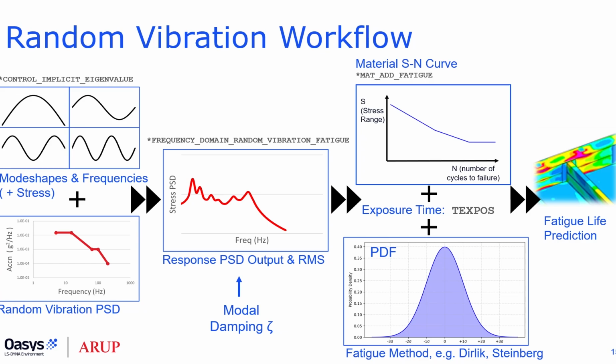With both methods, once we know the total damage, we have a good indication for each material whether it's likely to survive the test or not. But like all fatigue analysis, it's highly dependent on good data for the SN curves, and we have to take care with the model refinement, especially around details like welds.